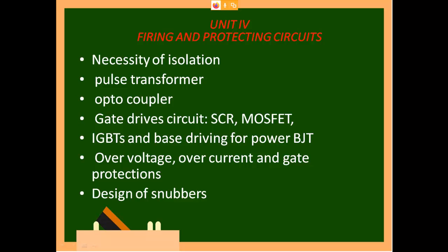So how to look into over voltage? Similarly, when you suddenly turn on, the voltage has to come to 0 and the current has to increase. Since you are operating at a very high switching frequency, and we all know for MOSFETs we will give 25 kilohertz or 30 kilohertz or 50 kilohertz, the same happens as in the turn off condition. For turn on, the current will go to 5 times its value, and this also leads to failure of the device, so you have to protect it. And the last one is gate protection, that is by proper isolation.